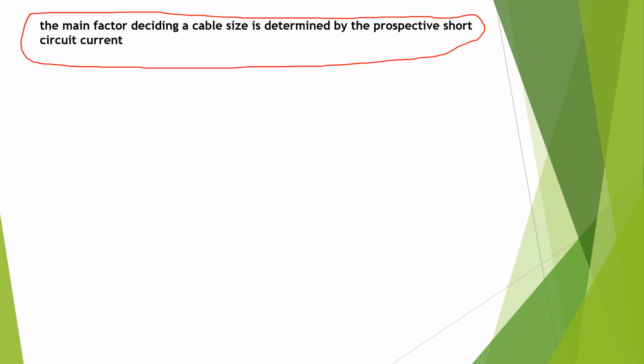In my experience, I've seen most of the engineers really don't know how to select the cable. They just go for the length of the cable, see that it can carry the amperage, never calculate the I short circuit, and also the prospective short circuit for the cable for half a second. That's never calculated and compared to the tables to get the correct square millimeter of the cable. This is a safe way to do it.